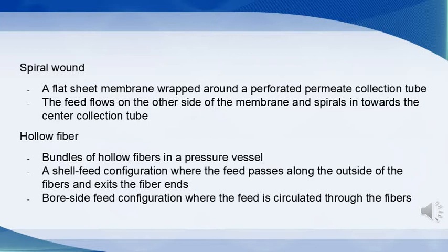The last one is hollow fiber. Hollow fiber filtration utilizes thousands of long porous filaments ranging from 1 to 3.5 mm wide. They are potted in place in a PVC shell. Each filament is very narrow in diameter and flexible. Hollow fiber can find use in all types of filtration.